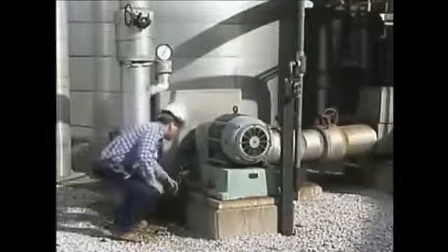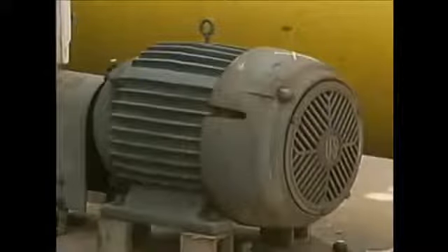In addition, listen for unusual sounds. A properly operating motor should make a smooth, steady sound. Excessive noise, knocking, or popping can be a sign of a problem. In addition to looking and listening for symptoms of motor problems, you can also use your sense of smell. Unusual odors may indicate a problem. For example, overheated insulation has a distinctive scent that can indicate a problem, such as an electric short.